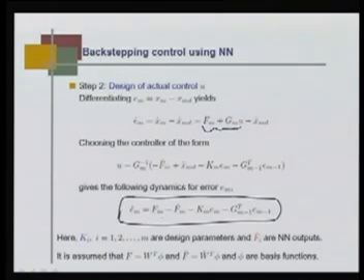em dot is fm minus fm hat minus km em minus g(m-1) transpose e(m-1), where ki for i equal to 1 to m are design parameters. The fi's are approximated by a neural network, and we assume that each fi is approximated by w transpose phi, such that the estimated one is w hat transpose phi, where phi is the basis function of the input.